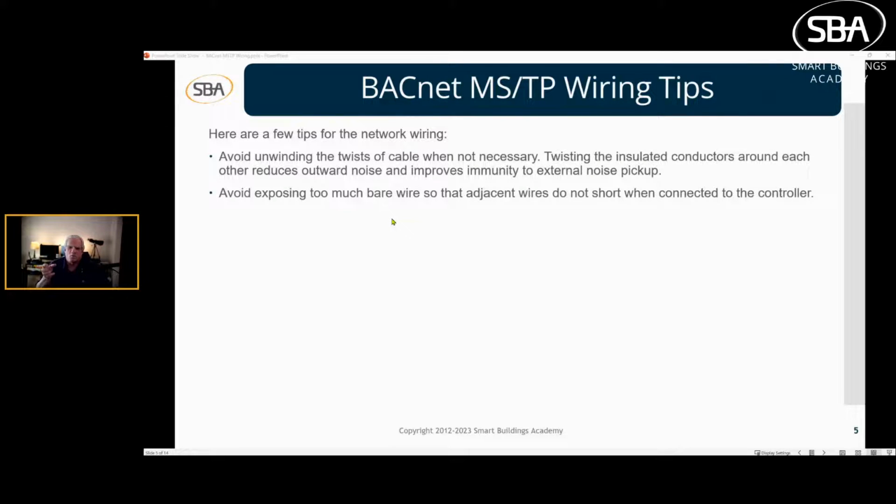Avoid using too much bare wire so that adjacent wires don't short when connected to the controller.